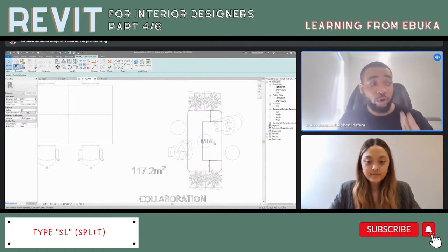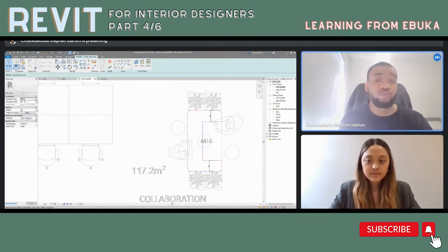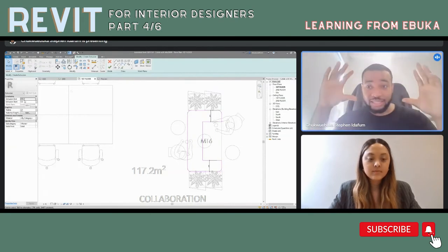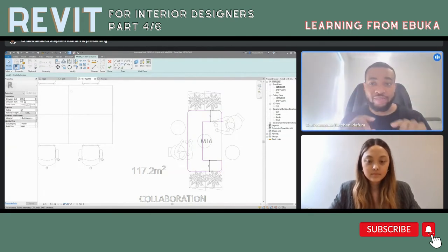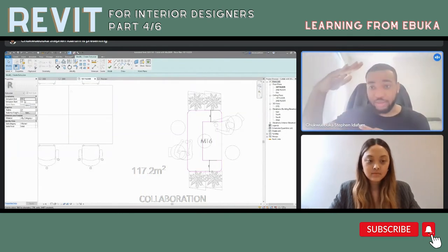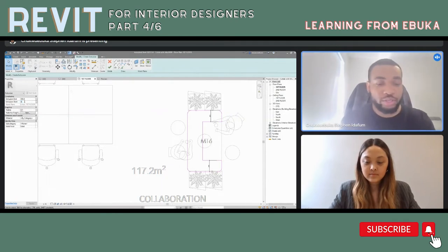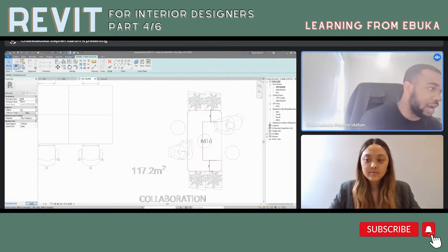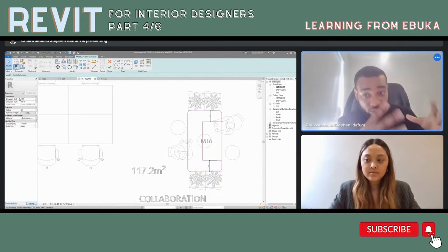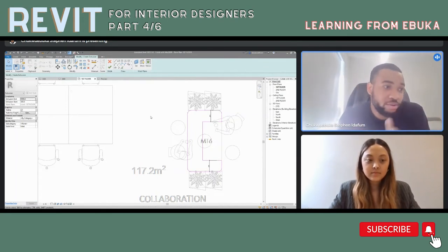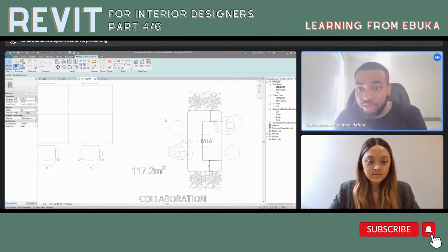Once you're happy with this, we want to know where it starts and where it ends. We have a base that starts from 0 to 300. So now we're going to start this from 300 to 1,000. We can always change this later. It's just showing you how to actually do it if you're modeling it for sale, because companies actually hire people to make Revit families.